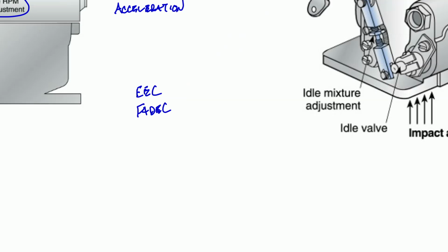And when we talk about, say, our EEC, so the electronic fuel control systems, or we talk about FADEC, either one, we're going to basically remove and replace. The changes and how it operates are going to come either from a different unit or from a software update or anything like that. So you're almost talking a little more of an avionics side of the world, where what you're going to be looking at are like BITE tests to check the internal circuitry or to check the software. It's all going to be computer based effectively.